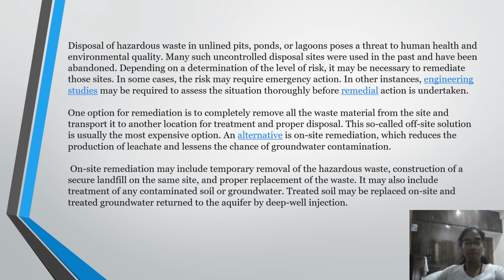On-site remediation may include temporary removal of the hazardous waste, construction of a secure landfill on the same site, and proper replacement of the waste. It may also include treatment of any contaminated soil or groundwater. Treated soil may be replaced on-site and treated groundwater returned to the aquifer by deep well injection.